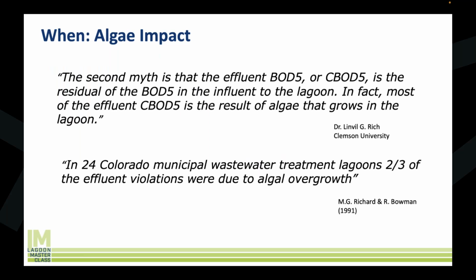So think about that. It is not that the lagoon, in a lot of cases, is failing to treat the influent load coming from the collection system, the pee and the poop, or in the case of an industry, the byproduct from your process. It's not failing to do that. It's doing that. It's just that algae is growing in the lagoon, which is then flowing out of the lagoon and showing up in your sampling as BOD, TSS, phosphorus in some cases.